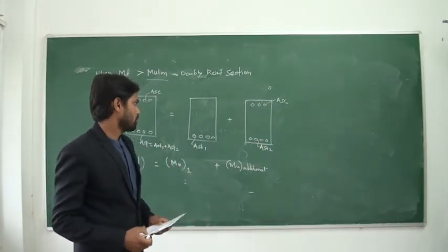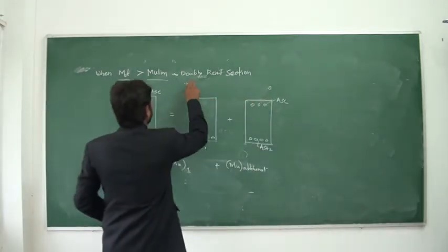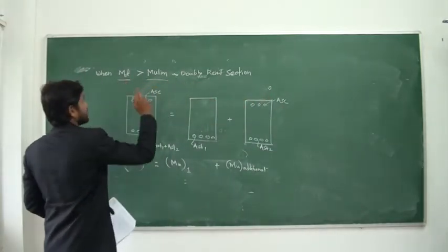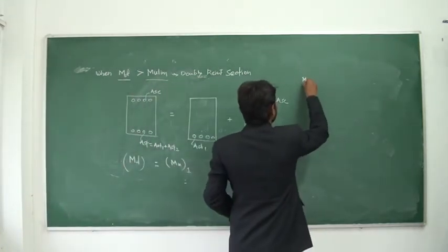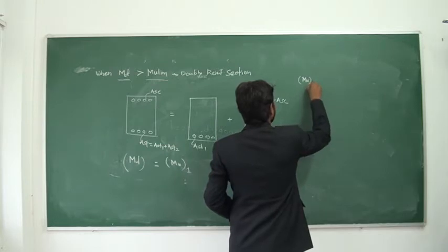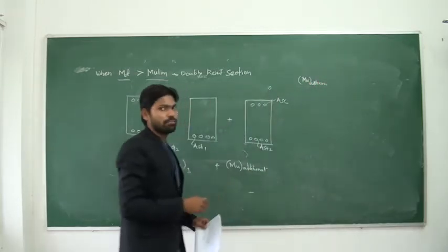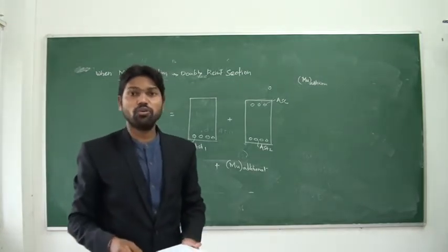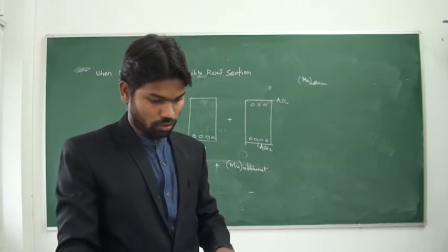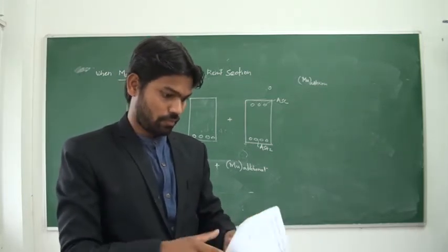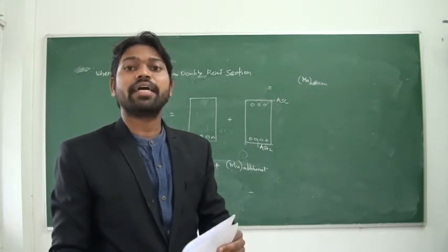So we will see. As we know, we provide the doubly reinforced section when MD is greater than Mu limit. So in that case, what is the additional bending moment? Mu additional means extra. Just now we have seen the example where the Mu limit value was 101.56 and I had taken MD as 150.